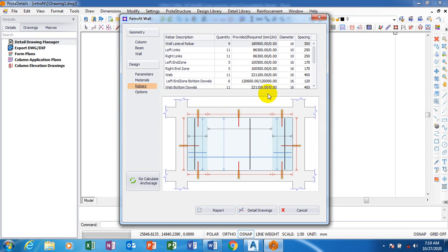You can see the diagram here showing you everything, well explained. You can see this is your bottom bars here. It has a return here. Now look at the return here. Now we have a reinforcement here, and all that. You can do all of that adjustment here if you want to. You can see this dual here has failed, so I can change that to 300.